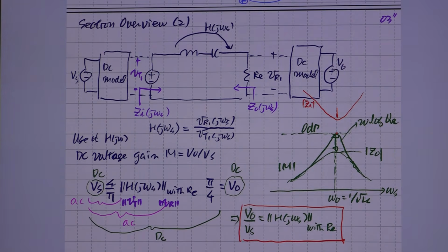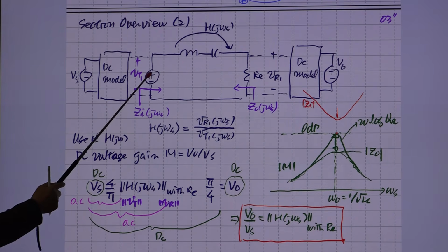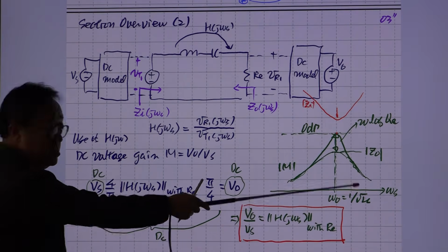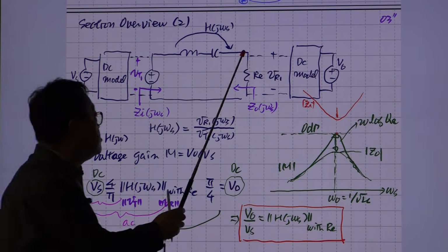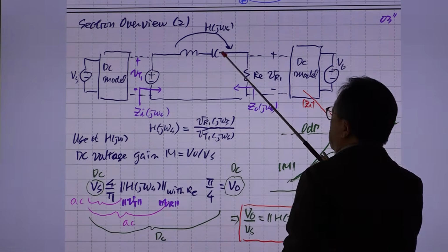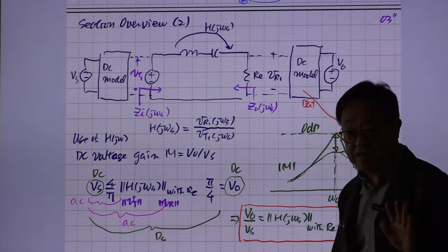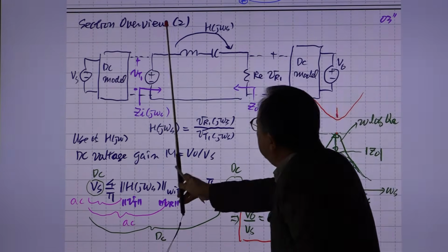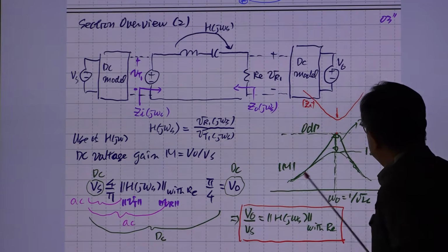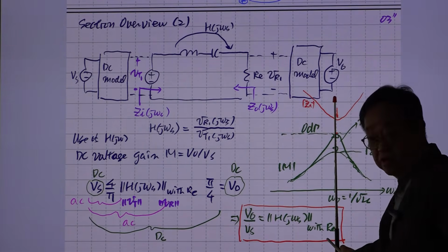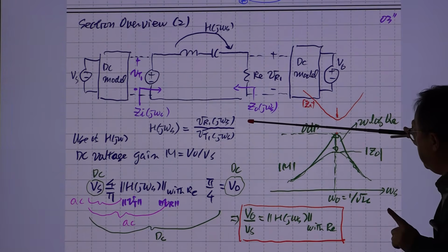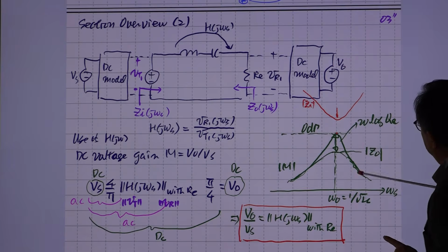With this, later on, we plot this magnitude curve from input voltage to output voltage. The AC response is this. As I said, at the resonant frequency, the reactances of these two reactive components cancel. They are not existing, directly connected. Then this voltage must be the same as this. So if the switching frequency is exactly at the resonant frequency of this tank circuit, this magnitude should be 1, just 1, 0 dB. And it shows this resonant behavior.